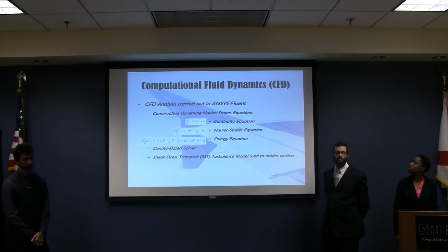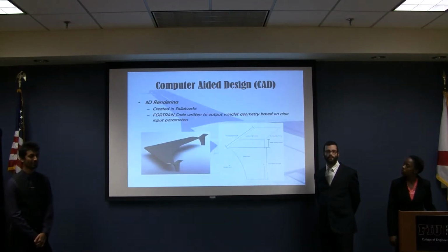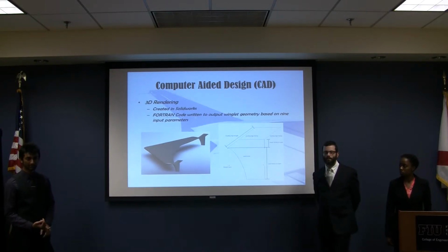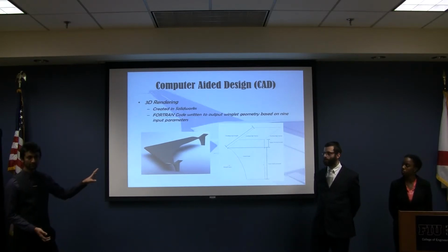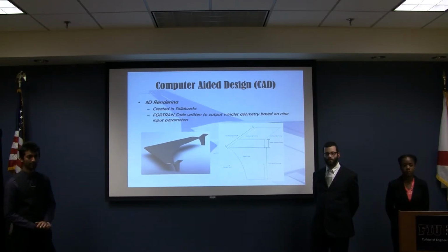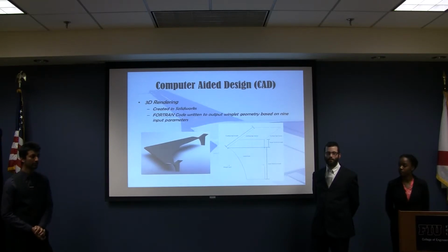Now, on the analysis and the CFDs and all of that, the density altitude effects, to what extent was that included in the modeling? Okay, so Fluent lets you specify density and kinematic viscosity. We're modeling the 2D PSU airfoil, as you saw. So temperature is also taken into account? Fluent lets you do that. Density altitude is impacted by both temperature and pressure. Exactly. Yes, it gives the option to input the temperature. So did you do that, or will you do that? We will take it into account.